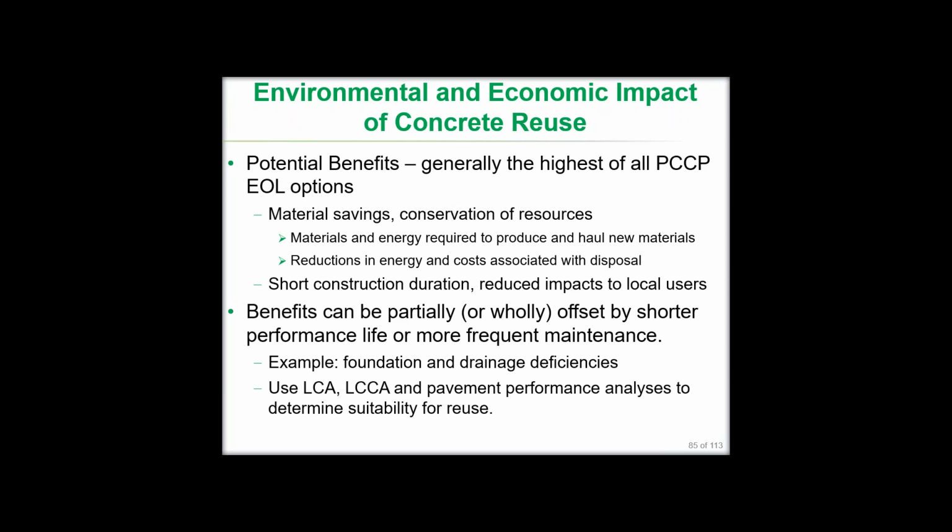As Hassan noted, these benefits can be partially offset or even completely offset if we have a shorter performance life or more frequent maintenance is required. And examples where this comes into play typically are when we reuse a pavement without addressing inherent foundation or drainage deficiencies that are going to shorten the life of whatever we do on top of it.